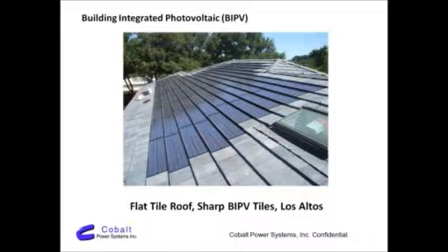And I think BIPV is a great idea for new construction, especially for tract homes, but I would say for custom homes or for existing retrofit, I generally don't recommend it, because you end up taking the tile off and then you have to do something with the tile, and you're suffering the cost of the tile that you don't need anymore, and again, it's low efficiency and expensive. But anyway, that's a BIPV example.